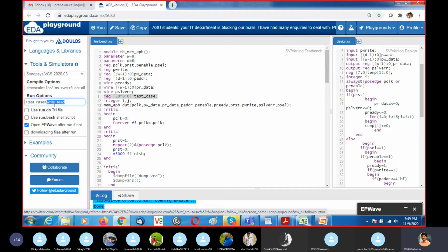How can I accept these words here? String data type is not available in Verilog, so each character needs 8 bits. So I declare this as reg [8*30:1], so it can accept up to 30 characters.